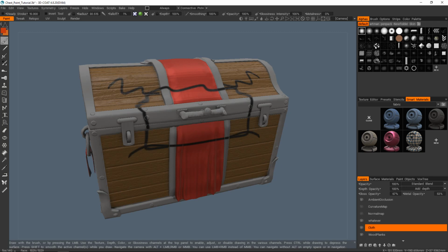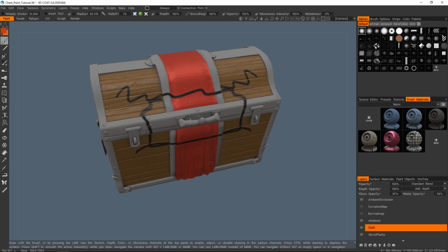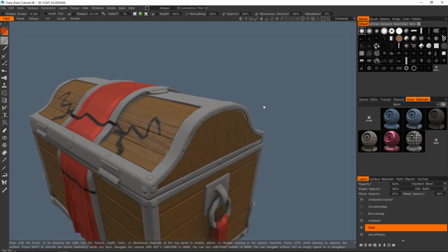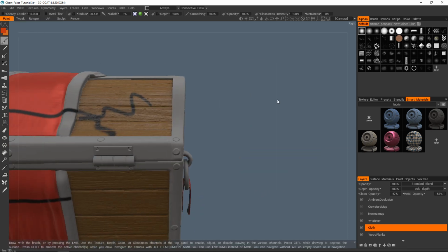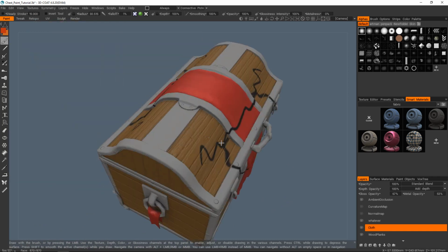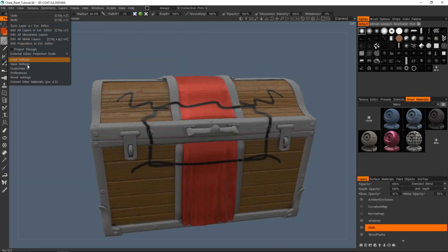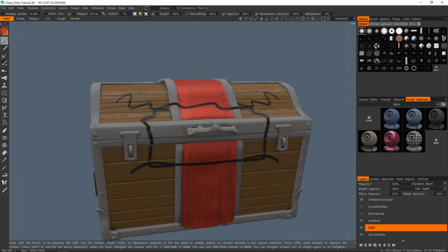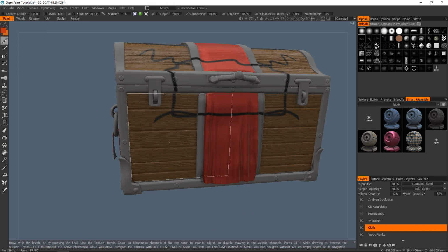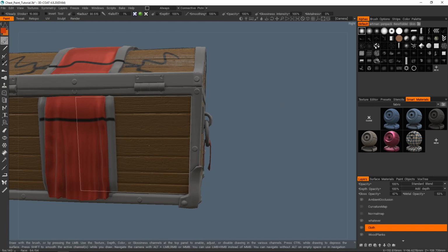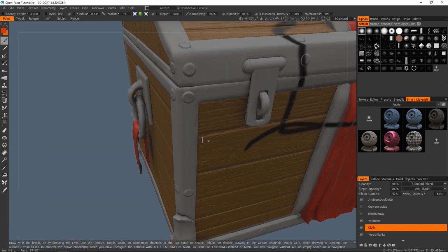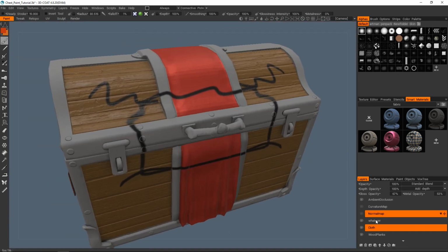Obviously it looks a bit different to what I just did because my UVs are mirrored, but the reason you would want project through off is not obvious because of my mirrored UVs. If you have this project through feature enabled, and I were to draw, let's say, a circle here, it would project through to the back. So for the most part you probably want to turn that off.